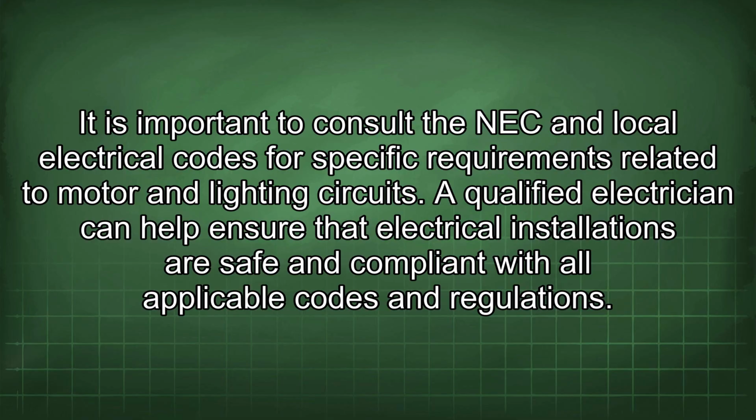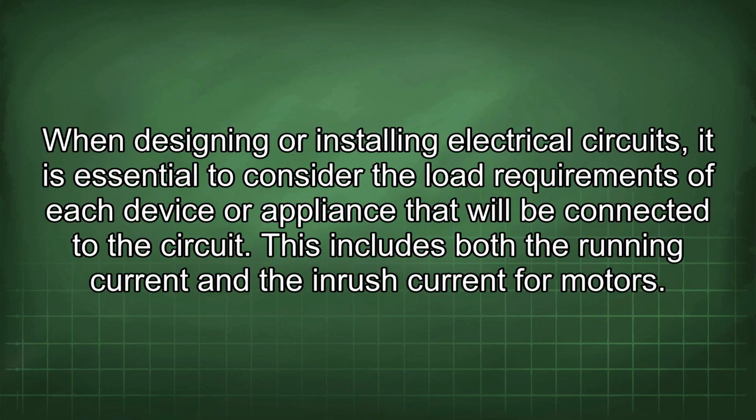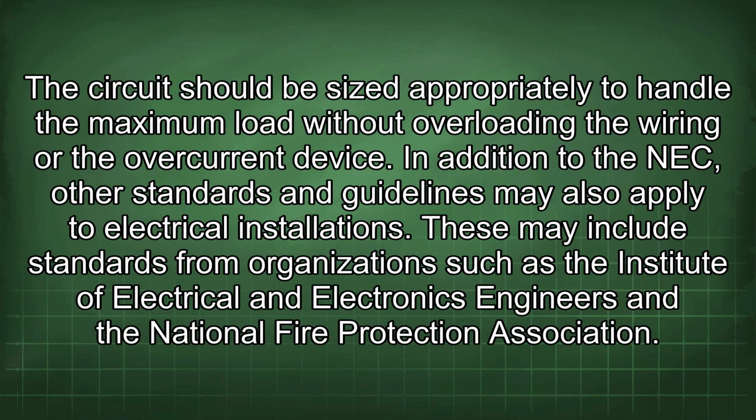motor and lighting circuits. A qualified electrician can help ensure that electrical installations are safe and compliant with all applicable codes and regulations. When designing or installing electrical circuits, it is essential to consider the load requirements of each device or appliance that will be connected to the circuit. This includes both the running current and the inrush current for motors. The circuit should be sized appropriately to handle the maximum load without overloading the wiring or the overcurrent device.